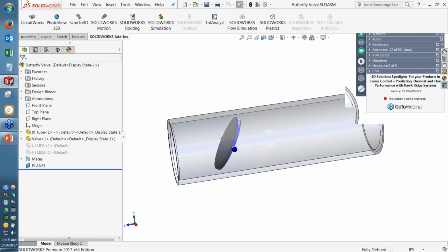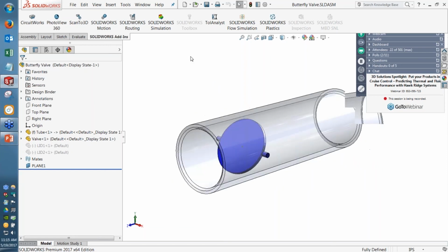If you put some loads on it, or gravity or springs, it can predict not how something deforms, but instead how the parts would either move around freely in space or would move mechanically based on the mates that you put in. And it's useful for deriving things like reaction forces or motor requirements or speeds or accelerations. So it's not typically used to predict product failure, but it can in some cases predict how a product will move. So let's take a look at how that might work.